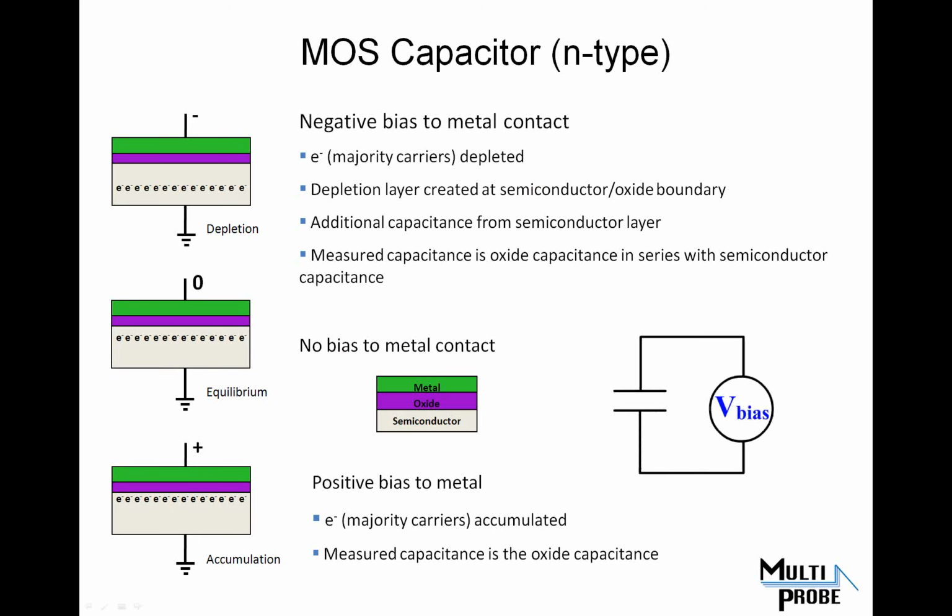We've put in a little flash animation to show the bias changing, and then effectively some capacitor plates moving, as I was talking about. And those are represented by the depletion in, say, this N-type semiconductor, where I'm depleting out an area, or I'm bringing it to equilibrium, or I'm accumulating it.